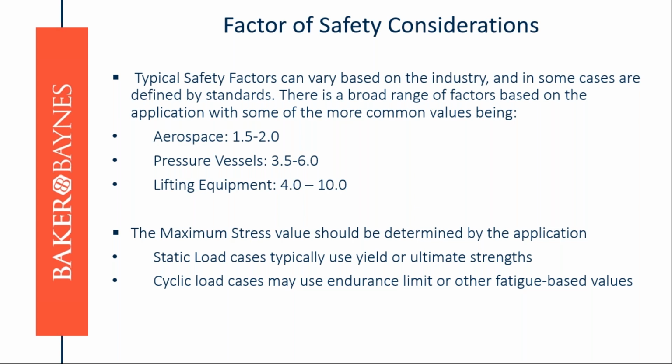And you'll see that the maximum stress should be determined by the application again. So depending where it is, it should be the application that is being used. That's where you'd find the maximum stress being used, and that's where the safety factors are determined, right? If we look at the load, static load cases typically used for yield or ultimate strengths, cyclic load cases may use endurance limits or other fatigue-based values. So depending on the material as well being used.